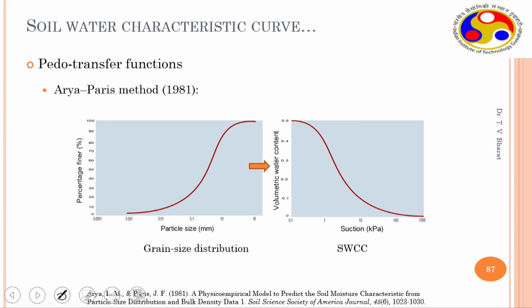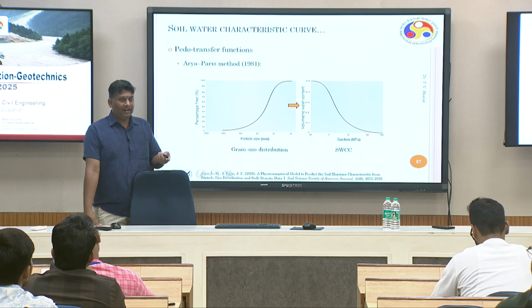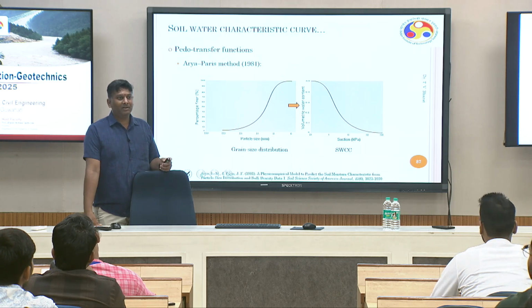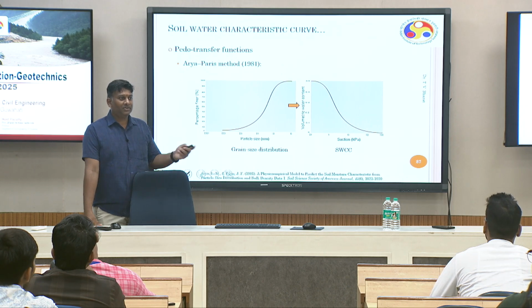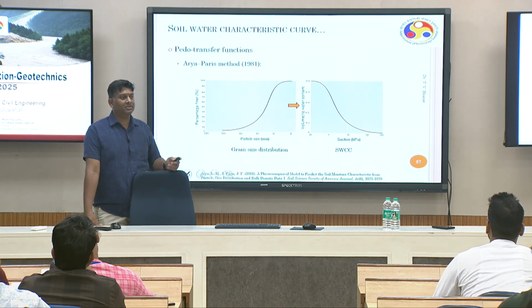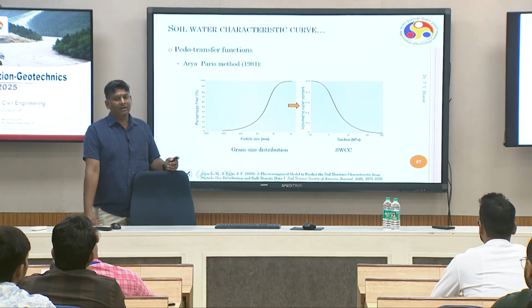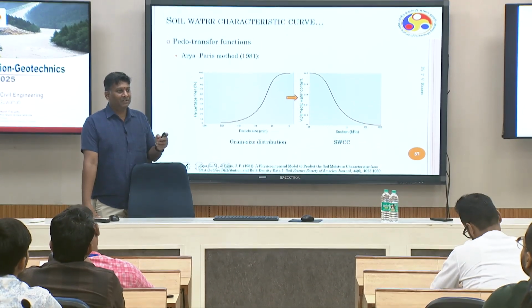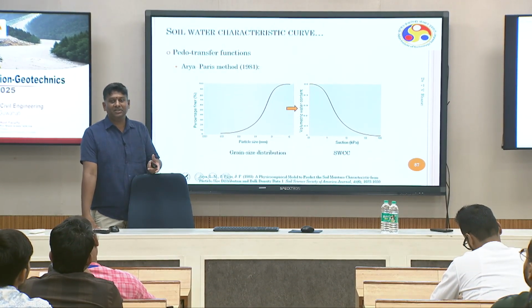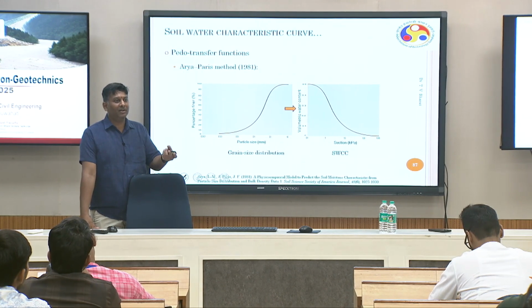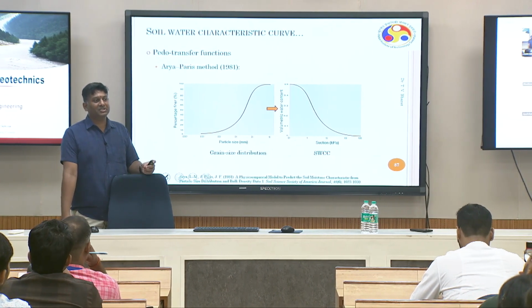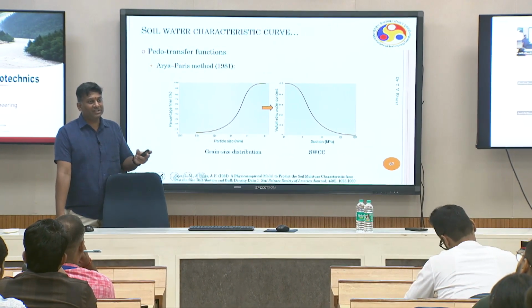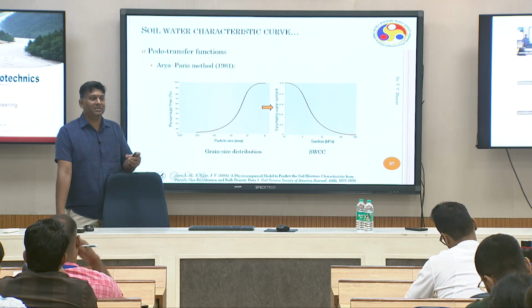So why is the SWCC required? We have many participants from industry. In landslides, for example, if you want to understand how the failure is happening, the first and foremost thing, I think, is to have the SWCC, right? Because when wetting takes place, the suction changes. From the suction, you can evaluate how the shear strength is changing. And when shear strength changes, the factor of safety itself changes.